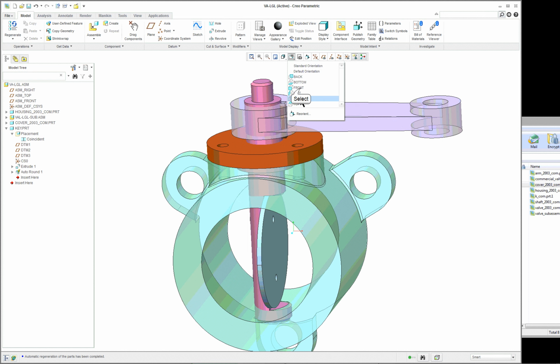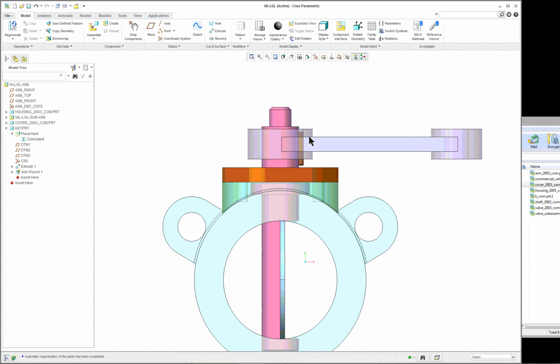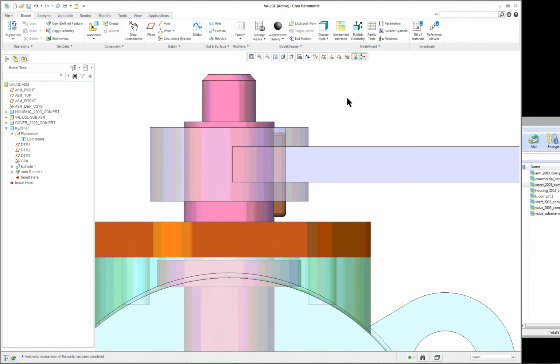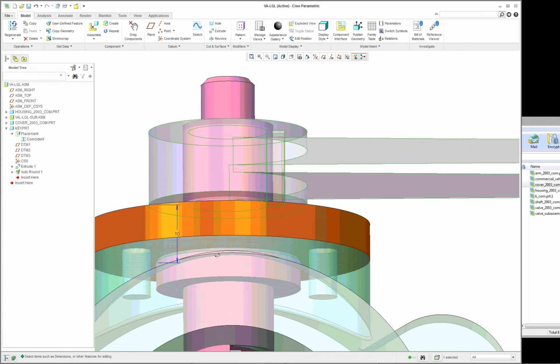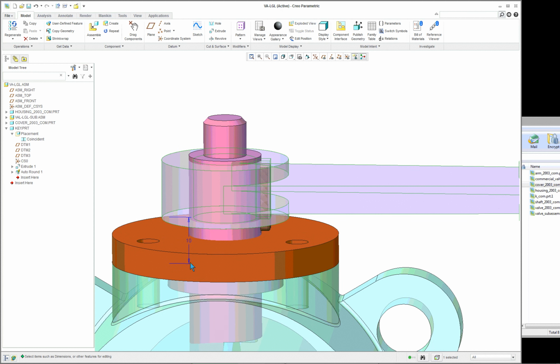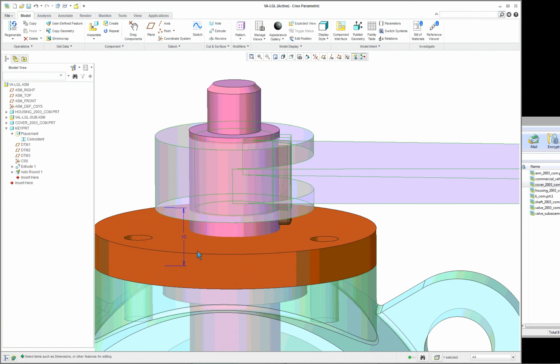Let's go into our front view here. And now you see where it's positioned. Now, there normally would be another washer or something here, and you can design one and put it in if you wish. You have to make the key a little bit smaller. And you notice we're going from here to here. It's being set up all the way to the bottom there when I put it on. So it's not being referenced from the top of the plate.